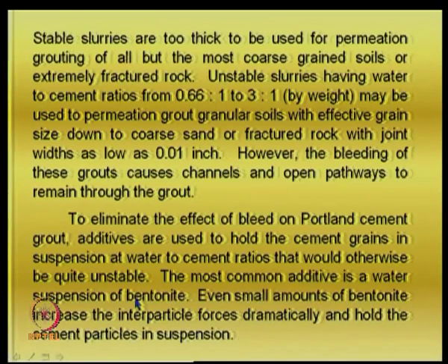As I just mentioned, we have seen that the bentonite helps a great deal. We know that bentonite is more like a repelling agent; the attractive forces are very minimal there. Bentonite particles tend to float easily in water, and when you mix it with cement it has a very good advantage. Even small amounts of bentonite increase the interparticle forces dramatically and hold the cement particles in suspension. Essentially, the interparticle attractions are separated.